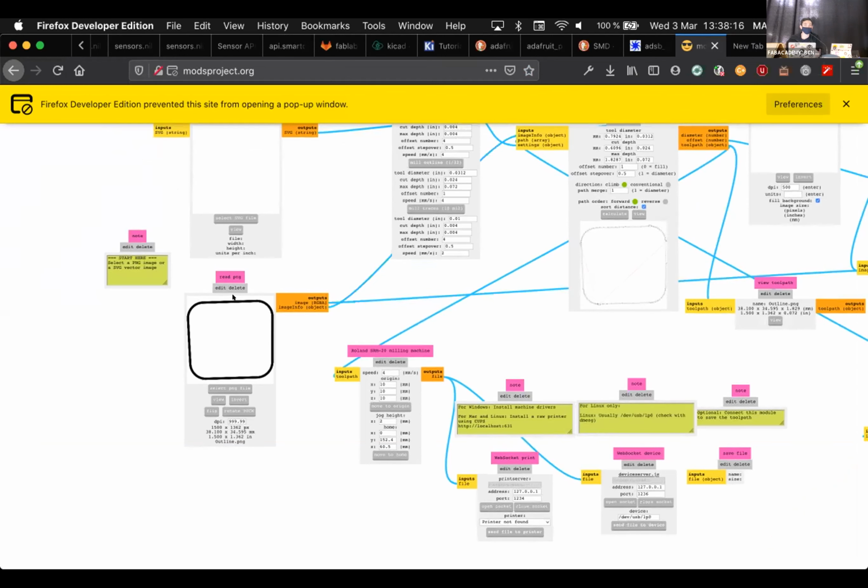So we have white on the outside too. Then it will try to cut the black from one side of the white and from the other one. So it will cut it twice. We don't want that because it will take more time, and also it will create a super thin layer of board that will pop out and can break our edit.